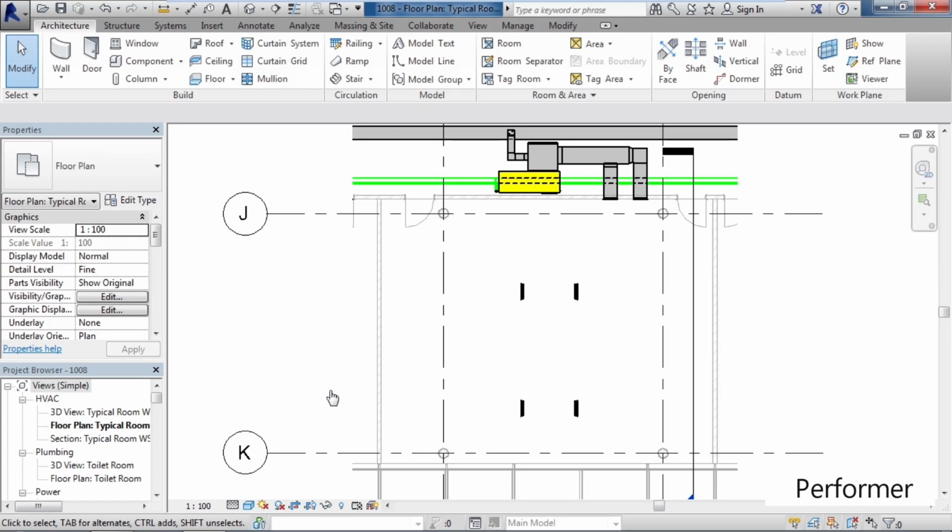So before you actually start to create all of these elements, you really need to define, or should define, a duct system. But first, you want to place a few components that base the duct system on. So in this example here, I've already placed 5 elements we'll use in this duct system. Four things I've created are the air terminals, the diffusers for which the air will come out of. The yellow box at the top is the actual mechanical equipment that supplies the air to these diffusers. So these five elements I want to add to my duct system before I start to create duct lines and duct accessories and actual other duct elements.